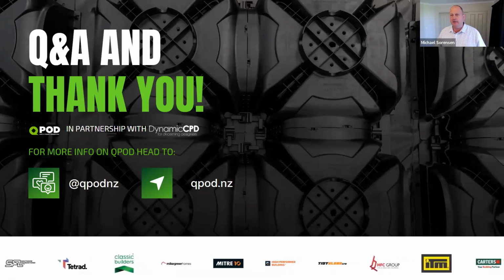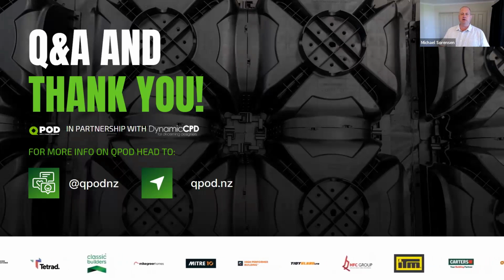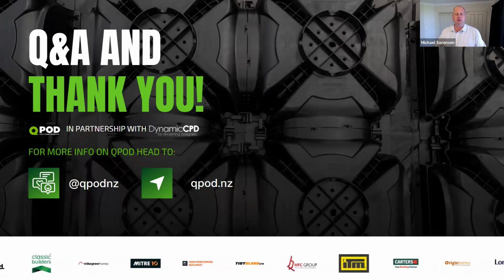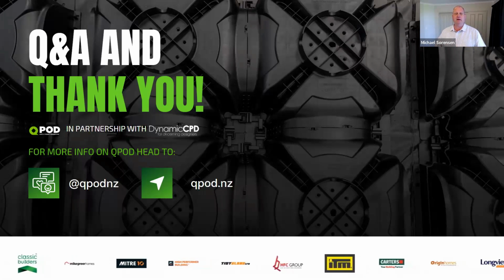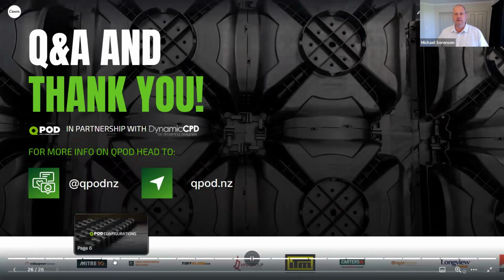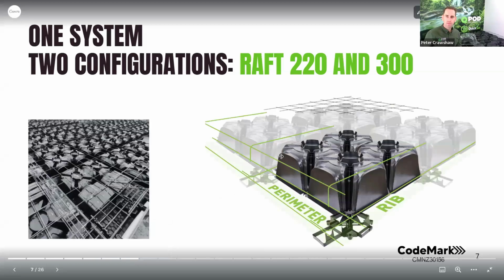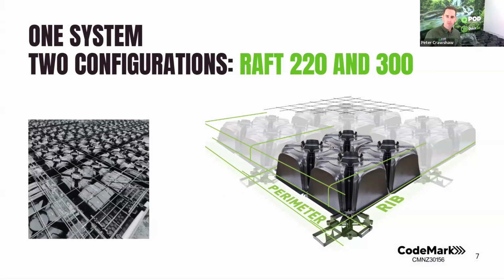Firstly, how much concrete cover? I notice you've got those little built-in bar chairs, so you don't have to add anything extra there with the mesh on them. And then how much cover do you have over that mesh? Yep. So minimum is 85 millimeters from the top of the pod to the finished floor level, and that built-in bar chair is sitting up proud 40 millimeters. So it's sitting your mesh right in the middle of that topping.